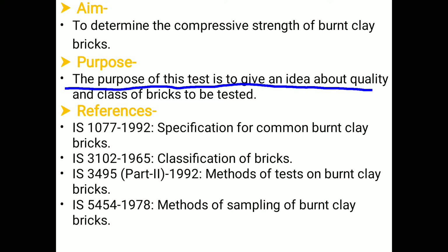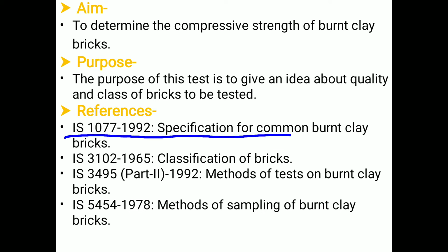The references are IS 1077 1992, specification of common burnt clay brick. The same reference we have used for the water absorption test and the efflorescence test also. The second reference is IS 3102 1965, classification of the brick.